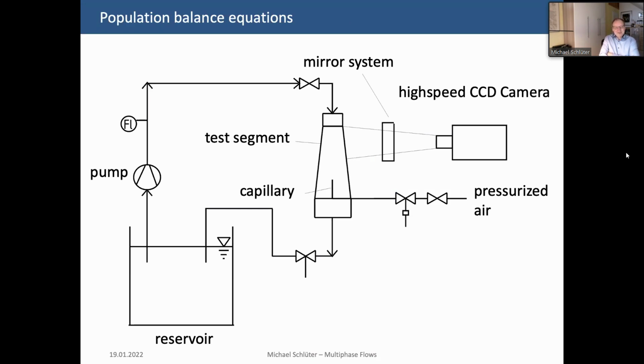And this is why we go another way, that we directly look for the bubble size distribution in the reactor in China and compare this with our watery systems. And we don't do these extremely expensive experiments with a strong effort, which might also be a little bit dangerous. But it would be nice to have this information for numerical simulations, because then we would be much more flexible to calculate even other geometries and so on.